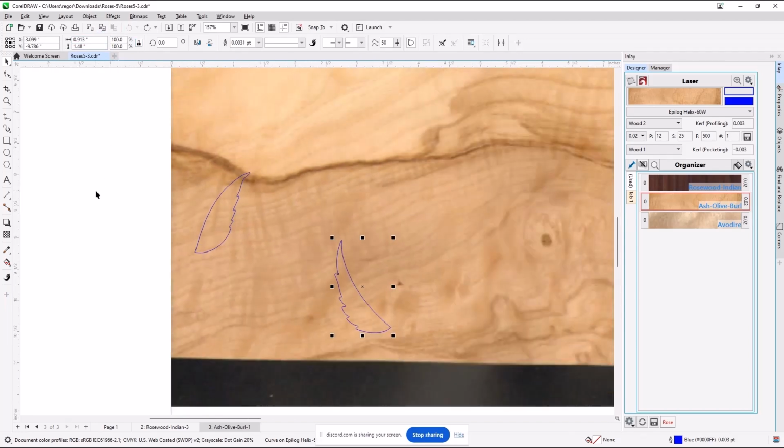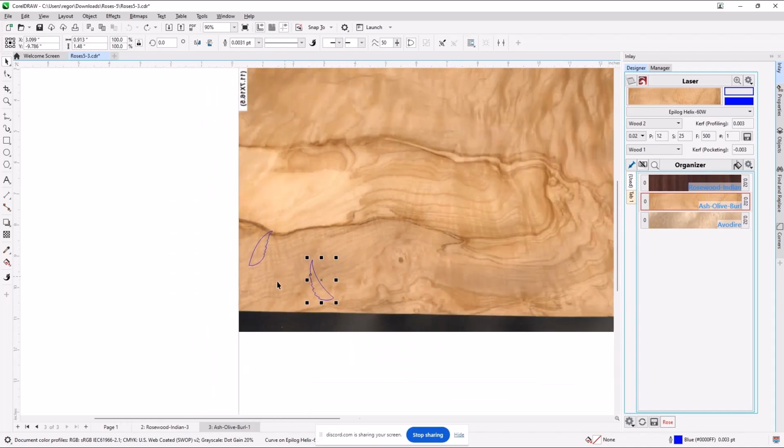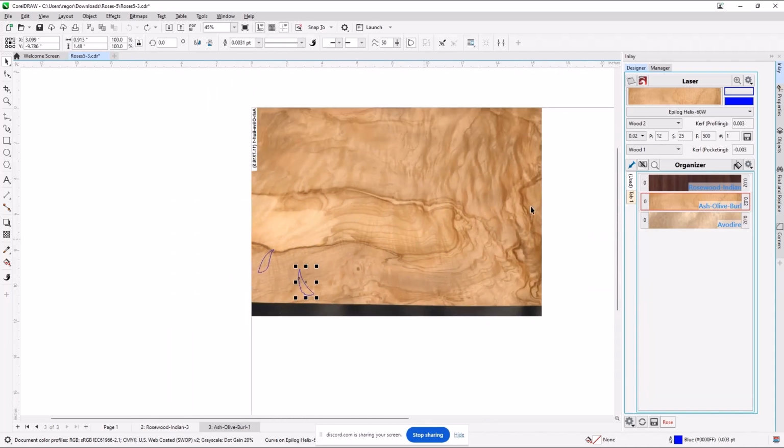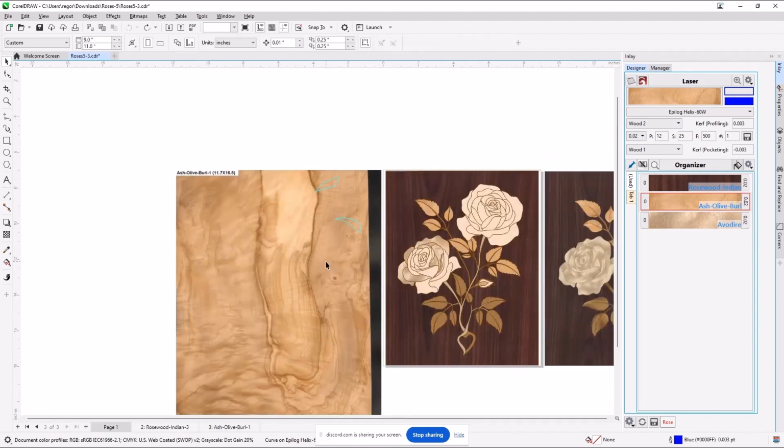Yeah, okay, this one is being mirrored cut. Let me explain that one. As part of the machine setup, if I want the best fit for the picture with the least gap, I'm going to want to make a mirrored cut. So I'm cutting from the back side of the veneer and I go to place them on the picture. I've corrected for the kerf so that these are literally mirrored, butting up against each other with no kerf at all.